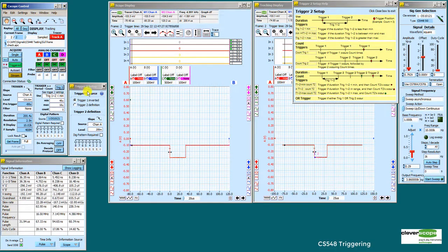Next one that we can do is we can trigger if the time between the triggers is in a range. So let's make this range 40 microseconds to 60 microseconds and put it in the range. And now it's not triggering because it's too short, so we'll extend it. So now it's from 40, it stops triggering, 60, stops triggering again, so it's just in the range.